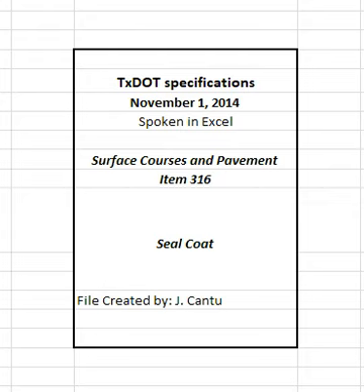If a tack coat is specified when using asphalt rubber, unless otherwise shown on the plans or approved, furnish CSS-1H, SS-1H, or a performance grade, PG, binder with a minimum high temperature grade of PG 58 for tack coat binder. Do not dilute emulsified asphalts at the terminal, in the field, or at any other location before use. If required, verify that emulsified asphalt proposed for use meets the minimum residual asphalt percentage specified in Item 300, asphalts, oils, and emulsions.